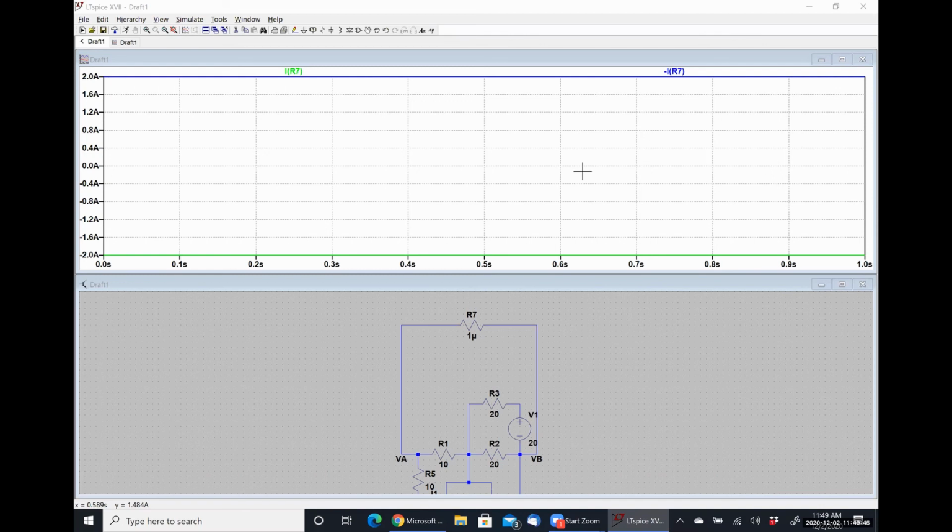I honestly don't know the answer to that. I haven't seen any tools like any multimeter tools or anything like that built in here. I think the easiest way personally would be to zero out all the sources and then apply a test source with a known voltage and then measure, or I guess if you put a 1 amp current and then you take the voltage drop over it, that will give you the resistor value. That, to me, would be the easiest way to do it. The closest thing to a direct resistance measurement. Yeah, there may be something built in there to do that. I have been too lazy to Google it. So if you find something like that, that's fantastic, use it.